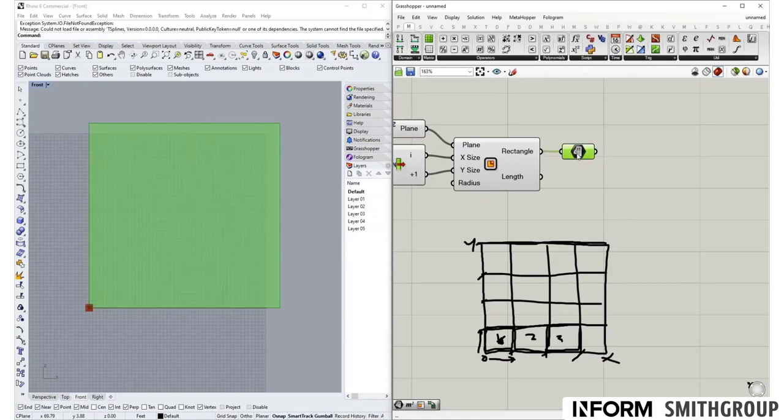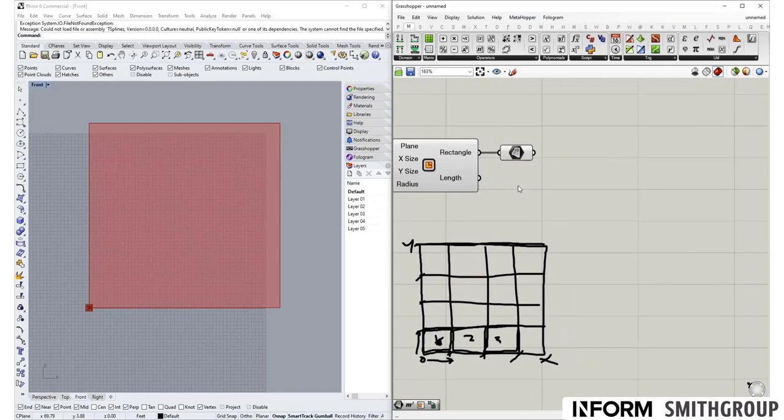Okay, so Grasshopper already recognizes when you pass a rectangle or a closed curved geometry into the surface node, it creates the surface. There are other explicit ways to create surfaces. Now that we have the surface, what we're going to do is divide domain, and we would connect this here.